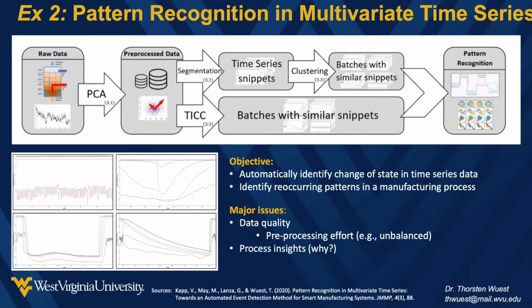And it's not like a bearing where you see a gradual decline. It might be just somebody presses a button or somebody shuts off the supply at another system that then has an effect here. But advanced warning would be important, because you have a 2-hour window. When your hopper goes under a certain level, you have 2 hours. After that, you have to shut down your injection molding machine or you produce scrap parts. And every company wants to avoid that, obviously.